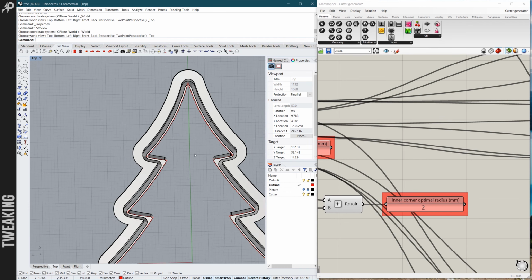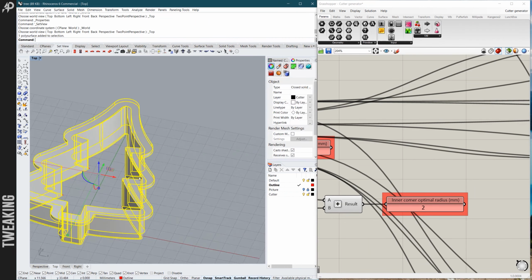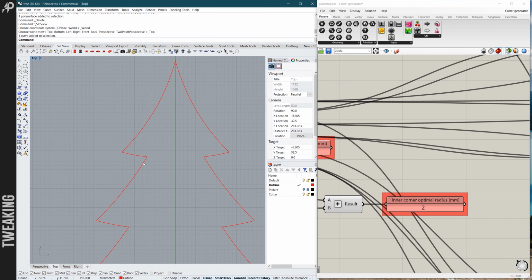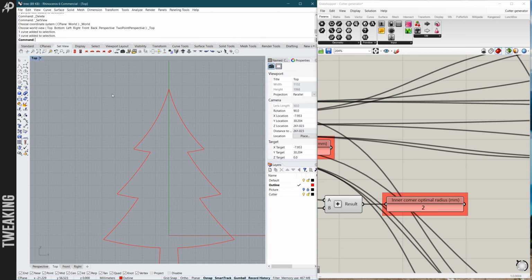So if we wanted to change it a little, just delete our old shape and have to re-edit our curve. So we wanted to give it a radius 2. So for this we can just use fillet function. Here we've got some instructions in the viewport. You always have a clear instruction and then some parameters that you may edit, and you use or edit parameter by pressing the letter that is underlined.